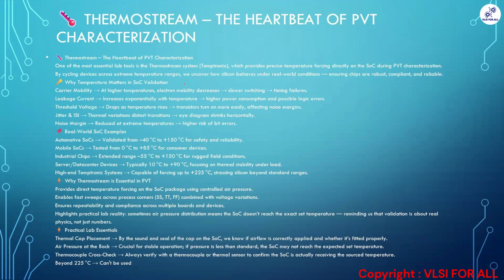Why it is essential in PVT: it provides direct temperature sourcing on the SOC package. And we have to see voltage variations as well. We'll be having some thermal cap, and at the backside of that we have to check the air pressure, because if we are not giving the correct air pressure, we are not going to get the correct temperature on the SOC.